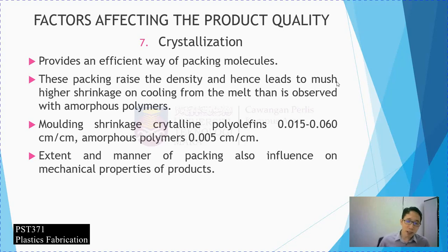So what I want to show here is that higher crystallinity polymer material will have a higher shrinkage rate. So you need to consider the shrinking behavior of this polymeric material, so that when you produce the final product, the dimensions of your final product will meet the required dimensions. The extent and manner of packing also influence the mechanical properties of the product.